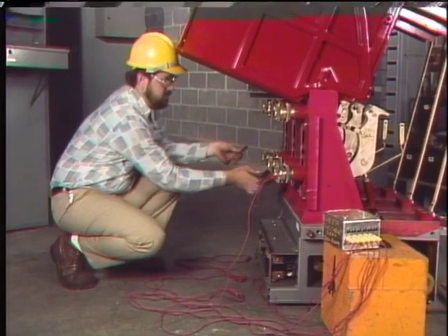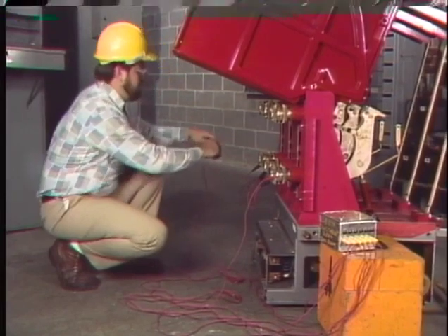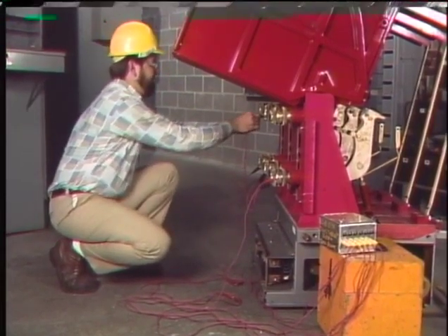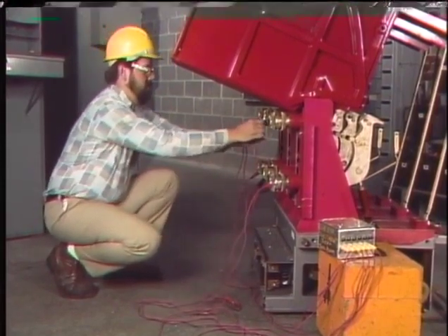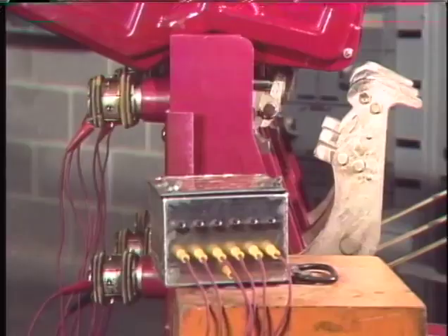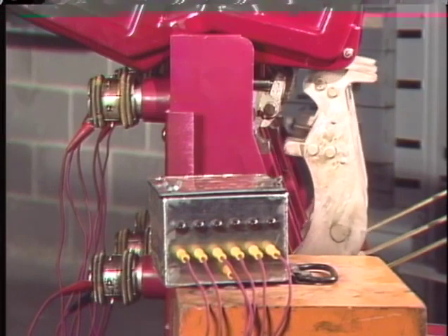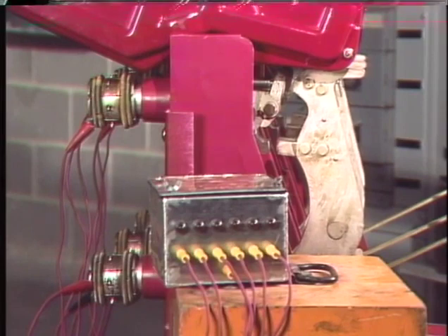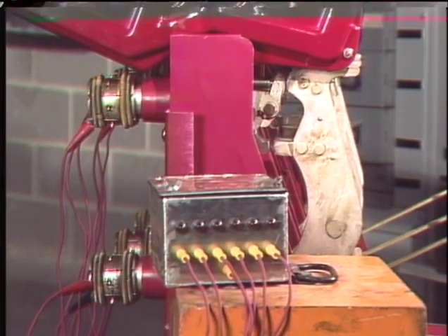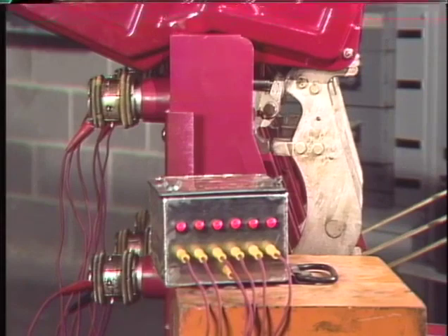One such device, a light-out device, is being applied here on the air magnetic breaker to show how it would be used. Leads from the light-out device are connected to each bus and line connection. On other breakers, they may be connected to the conductors at each bushing. After the light-out device is connected, the breaker is slowly closed. When the arcing contacts for a given phase touch, the light for that phase will light up. The contacts for all three phases should touch at about the same time, within a specified tolerance. If they don't, the contacts should be adjusted and rechecked.